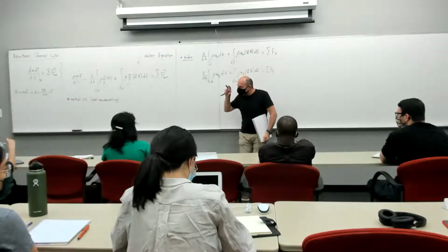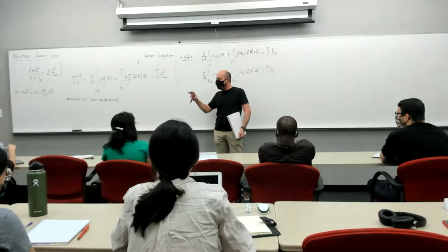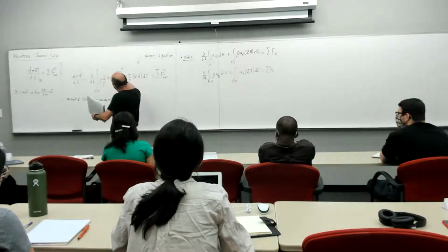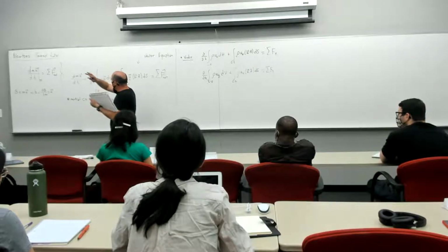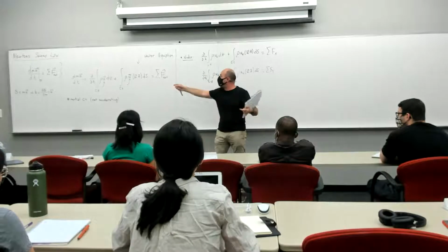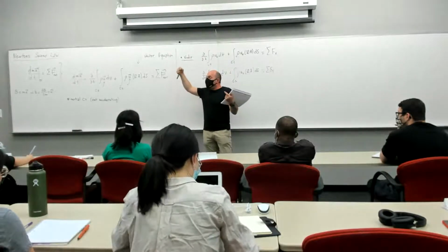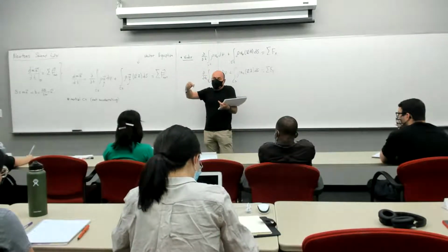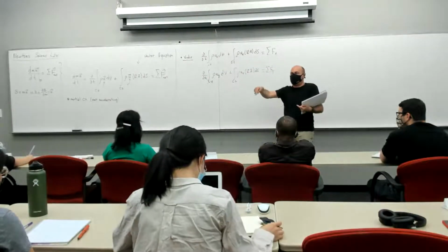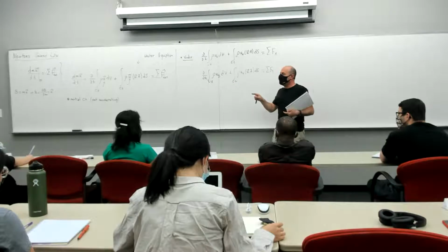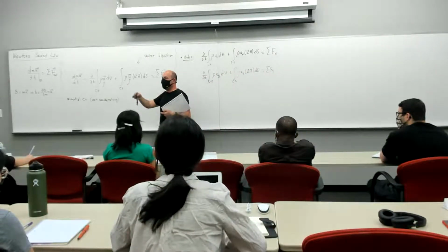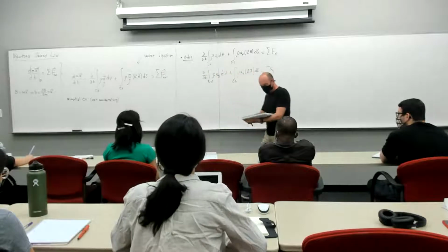Right? So because the system coincides with the control volume, this kind of tells you internally what's going on as the flux moves in and out, but the summation of forces, these are external forces. They're acting equally on the system as the control volume because they don't know if this is a control volume or a system. We're just acting in that region, right? So those don't change. That's why you don't see this right-hand side changing from Eulerian to Lagrangian. Okay?